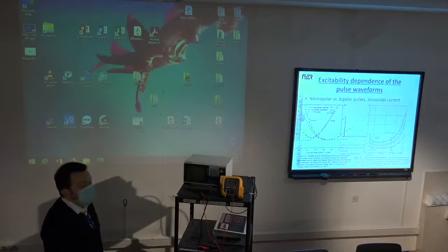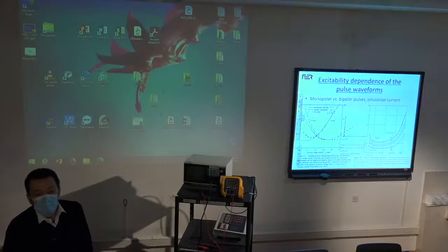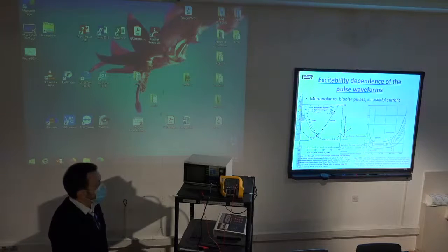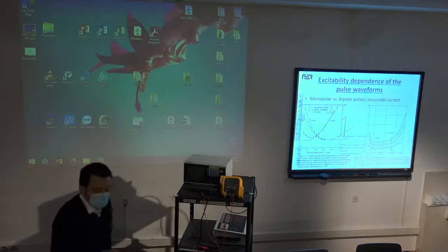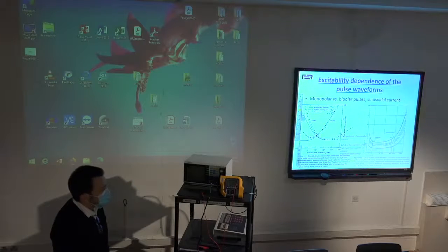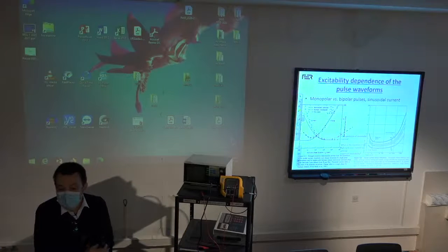The curves here are always showing the sensitivity for a particular current or current density. What we can see here is that frequencies around 50 Hertz, that's here, designate that the human tissue, that means heart, nerves, muscles, is most sensitive to frequencies around 50 Hertz.